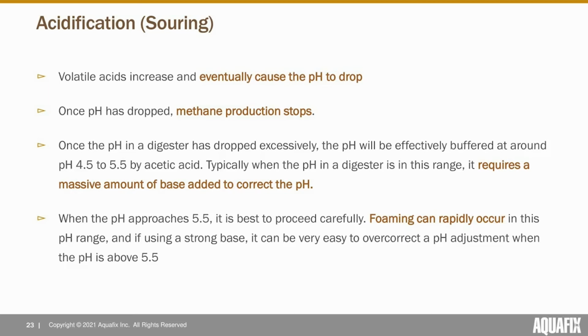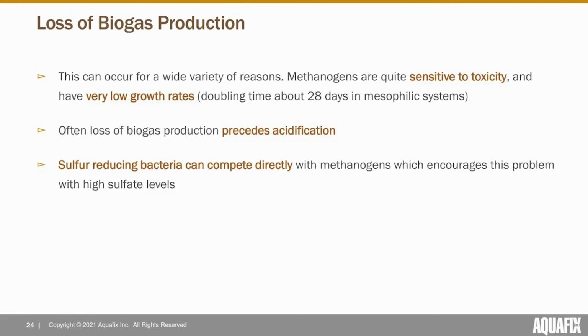And it's nice to add those simultaneously with the sodium hydroxide at first, so you start to establish a bicarbonate buffering capacity around 7, because your pH will not increase as quickly either if you have a lot of bicarbonate present.